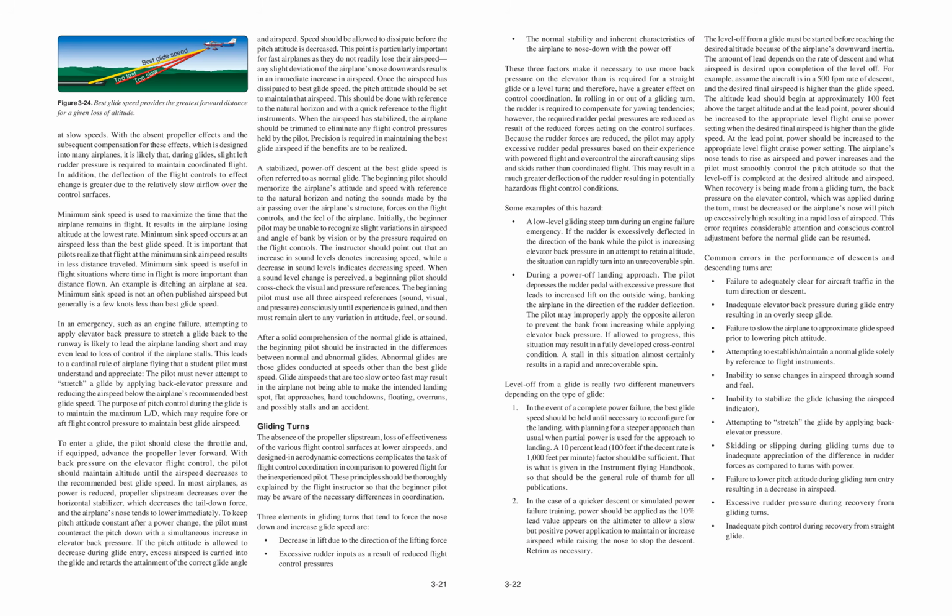In rolling in or out of a gliding turn, the rudder is required to compensate for yawing tendencies. However, the required rudder pedal pressures are reduced as a result of the reduced forces acting on the control surfaces. Because the rudder forces are reduced, the pilot may apply excessive rudder pedal pressures based on their experience with powered flight and over-control the aircraft, causing slips and skids rather than coordinated flight. This may result in a much greater deflection of the rudder, resulting in potentially hazardous flight control conditions.